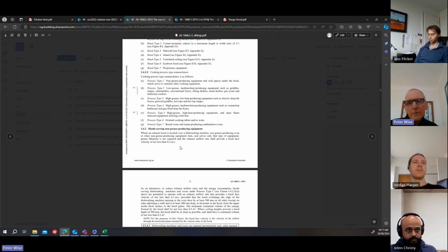So this would normally be a dishwasher hood. In a commercial kitchen, you normally have all your fryers and ovens and whatever they use in there, griddles. But there's quite often a dishwasher as well. A dishwasher does need to have an exhaust hood over it because it's producing vapour and heat, and that needs to be taken away. But a dishwasher hood does not need filters. It's just an open hood to take away the steam and heat.